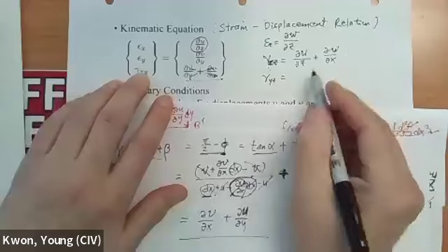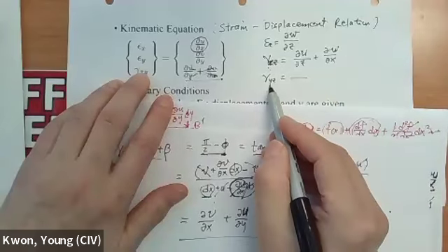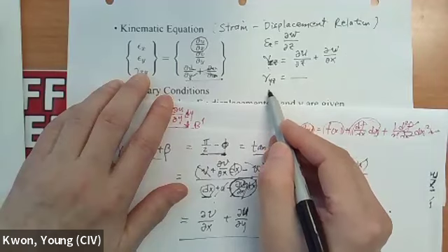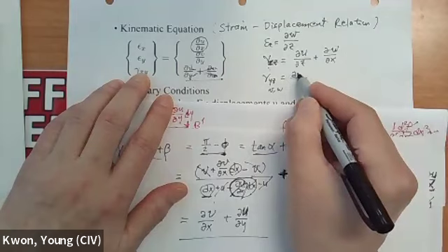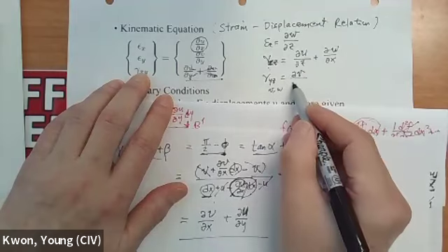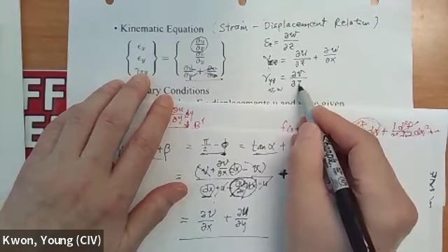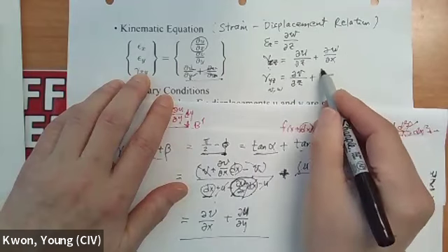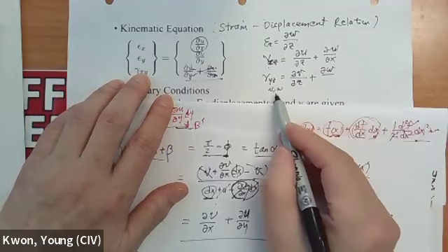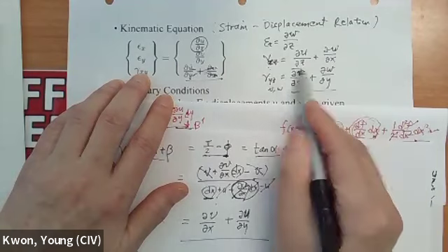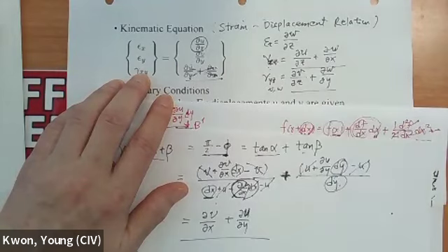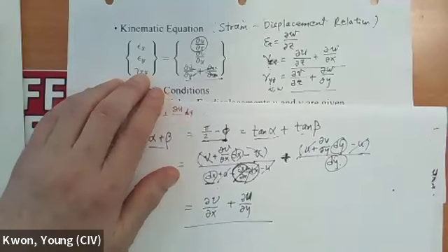Then let's do one more here. Now this is going to be the y and z component, so that's the v and w components in terms of displacement. So partial v, then the derivative is with respect to z, plus partial w, then the derivative is with respect to y. So that's going to be the shear strain in 3D. Okay? Any question?